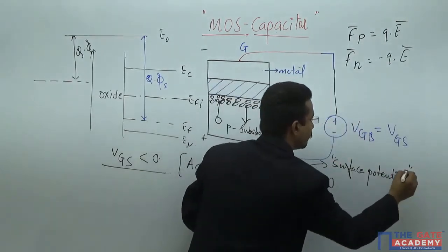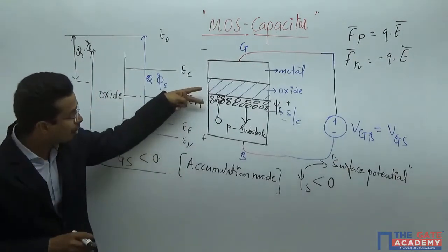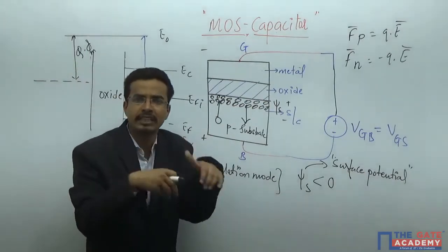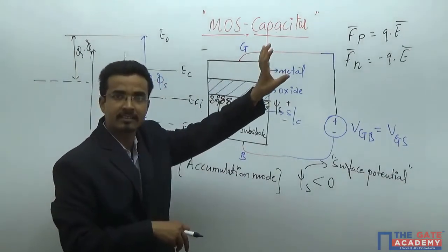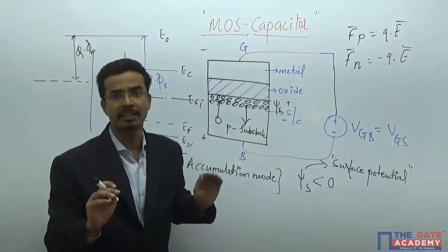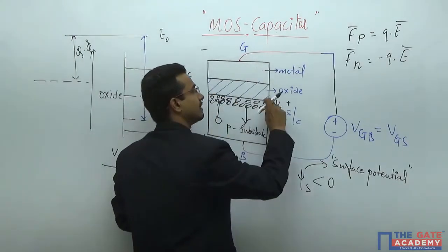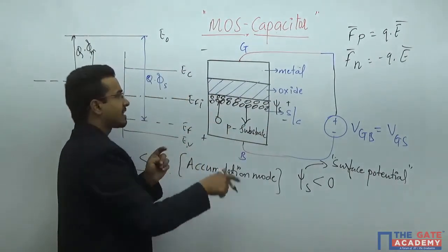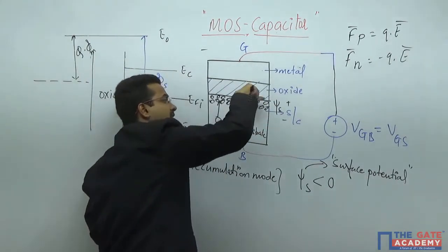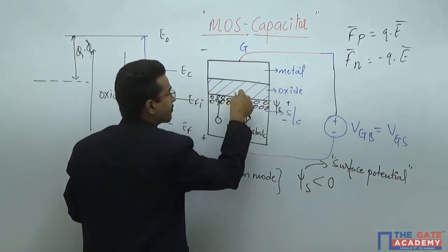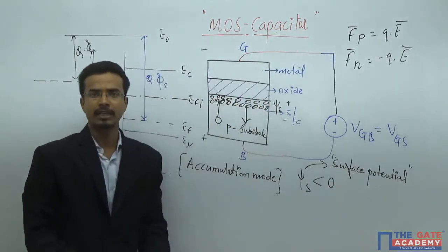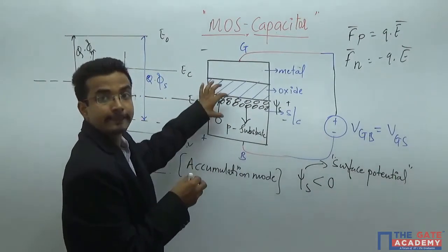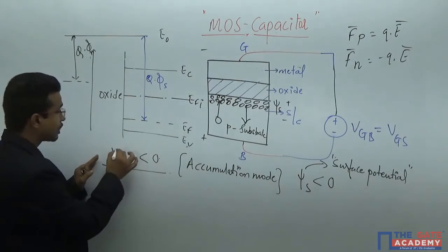What is happening with the charge carriers across this particular junction? Because whenever you go into the detail of MOSFETs, all the conduction parameters are just because of these charges. So I am not interested in the entire bulk. I am interested only in what is happening at the interface of the oxide and semiconductor, because the entire electrical behavior of this device will be decided by that. That means the first case, accumulation.